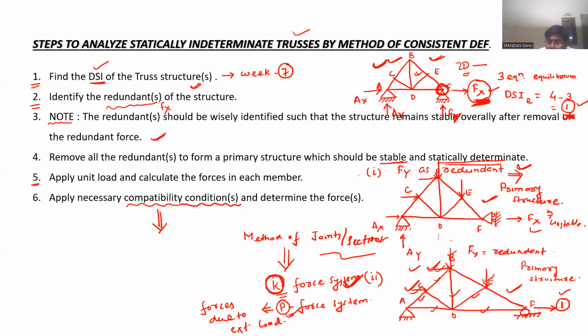So under these external loads, there will be some displacement. Let us say delta E. Due to external load, there is a displacement along X direction, that is delta E. Now, when you remove all those external forces and apply 1 unit load, due to this 1 unit load, this joint will try to move or not. Yes, sir. So I am writing it as delta U.